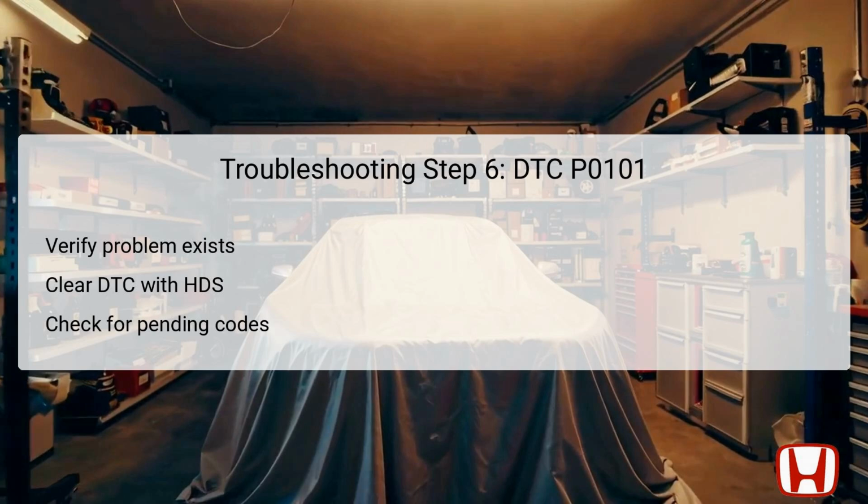If no codes are present, it suggests the problem may have been intermittent, so also check connections at the sensors and the powertrain control module, PCM. This thorough process ensures comprehensive verification of the MAF sensor system's health.